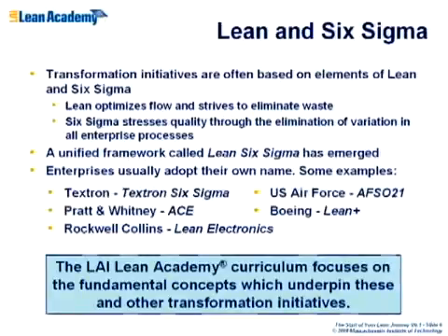So, I just came from Boeing helicopters. I was there for a week last week, helping them on the root end fatigue problem on the Apache attack helicopter advanced composite rotor blade program. And there's a root end problem, and I was there to fix it. But we literally take 6 specimens, which has nothing to do with Six Sigma per se, and then run out the fatigue test and determine what the high confidence, 99.999% stress level is that we can guarantee the life of the part. And so it's used a lot.